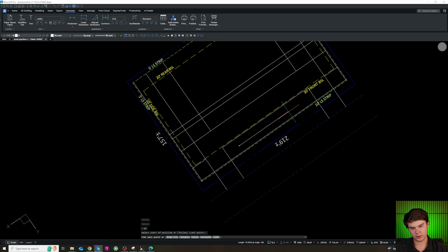I'd like to move this. After you've trimmed, the midpoint will be the center of this section. And now we know how far our islands will go. Now it's all centered up. Use a fillet with a 0 radius to connect these and connect this.